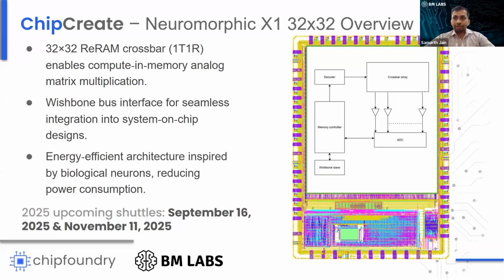Yeah. So actually for the wishbone, how it works is it has a data line followed by some CYC, strobe, acknowledgement. So the acknowledgement is the only signal coming from the slave, right? And the CYC and strobe are all controlled by the master. So when you want to write data using wishbone, first you have to make sure that you send the correct address of the slave on the address line. In our case, it was 3 followed by 6 zeros and a C, a 32-bit address, right?